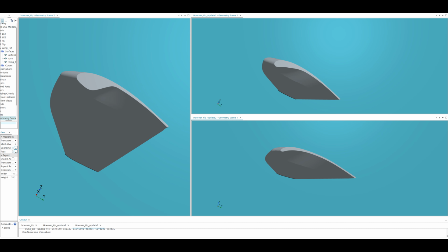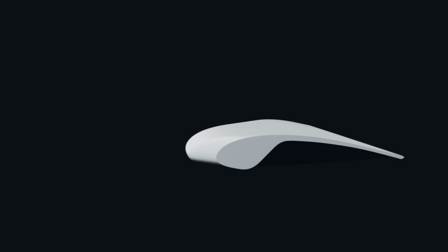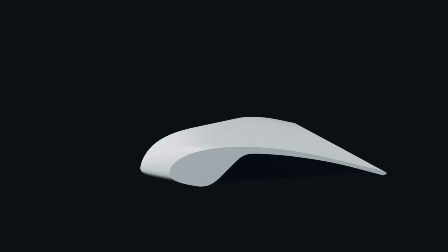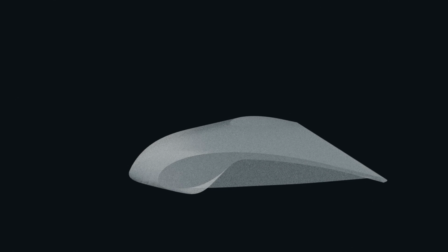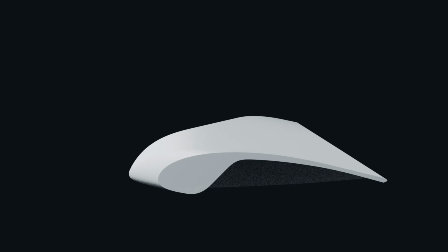To verify the impact of geometric fidelity on Hoerner wingtip performance, I plan to perform geometric iterations on the current model by constructing two sets of models with thinner edges that are closer to the theoretical design, and conducting comparative simulation calculations to quantitatively evaluate the aerodynamic gain after geometric correction. In the first optimization model, I focused on thinning the wingtip side edge, strengthening sharpness. Combined with literature analysis, this can force the airflow to separate at the wingtip position, thereby effectively reducing induced drag.